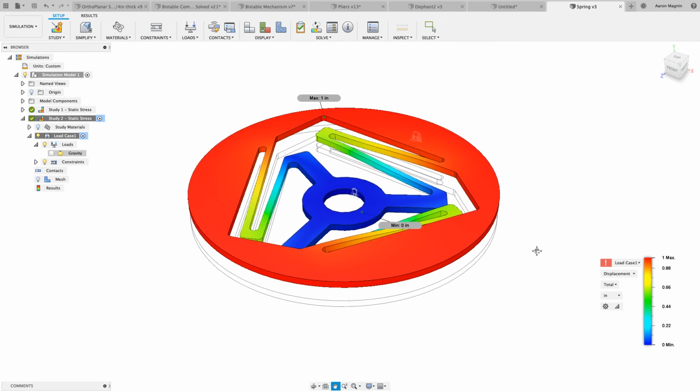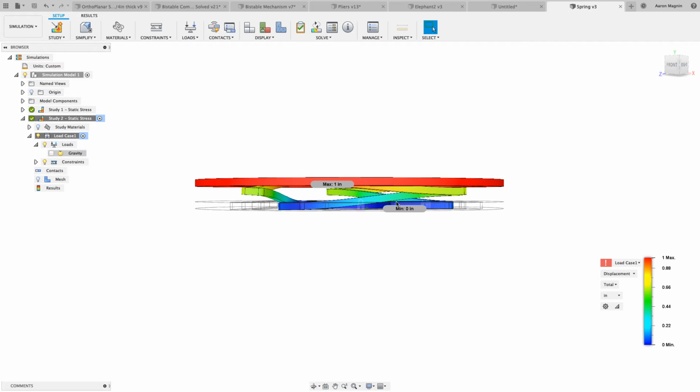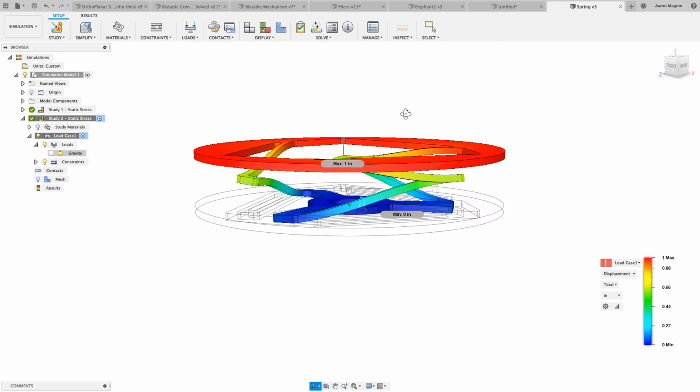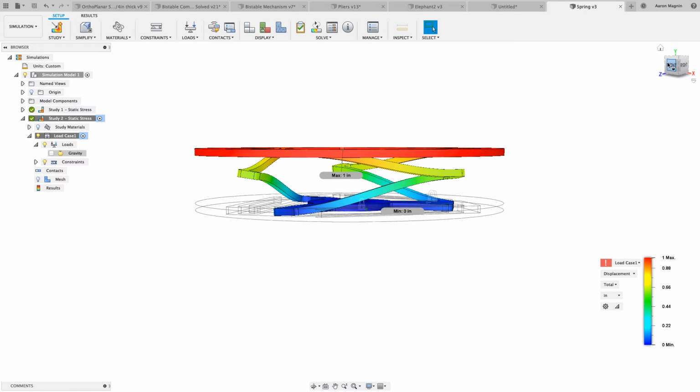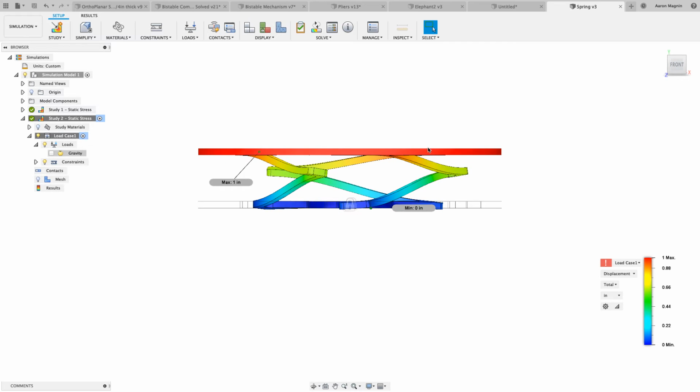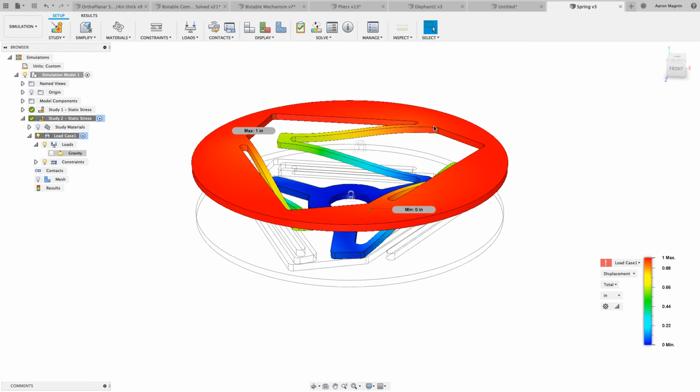I'm going to be able to extract this, and by the way, I do want to note that is not an inch of movement, right? That's part of that alteration that happens to make things a little bit easier to see, and sometimes it exaggerates things, and sometimes it actually scales back the amount of movement. If I move this back to the actual displacement, you can see, yeah, that's more likely an inch, right? If this is an 8 inch thick, then that's what I'd expect to see happen, right?